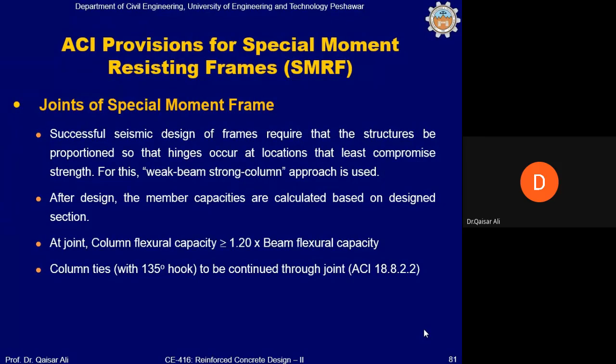Do you know that from the slide that we discussed in the beginning, that actions due to earthquake will occur around the beam column ends, at the beam column ends. So it will occur in the beam column joint, which is the common portion, and basically the joint part of the beam column connection is the part of column. Okay, because the load, axial load will be transferred through this joint. And then some part of the beam up to 2 inch on both sides of the beam, and L0 top and bottom of the column. This total portion is called as beam column connection, and the common part within the column is called as joint.